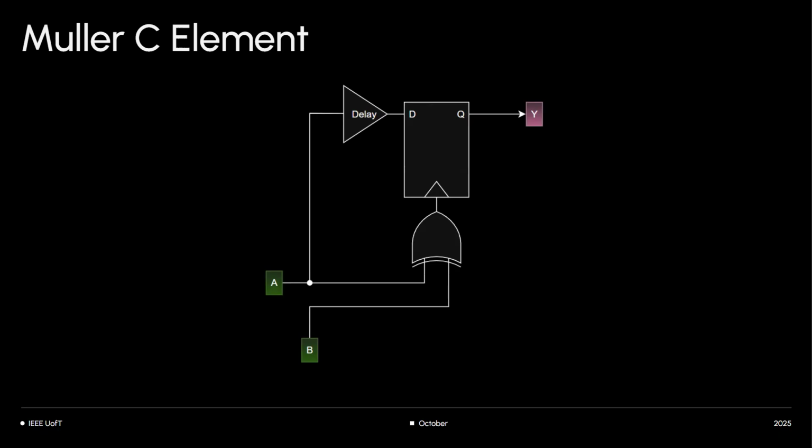There's a configuration set of bits that you have to have, but D-flops are more common, right? So I'm just using D-flops as an example. You can build it using D-flops. It's just that you have to hack the clock line a bit. And then there's a delay line. Delay is a buffer. Okay.